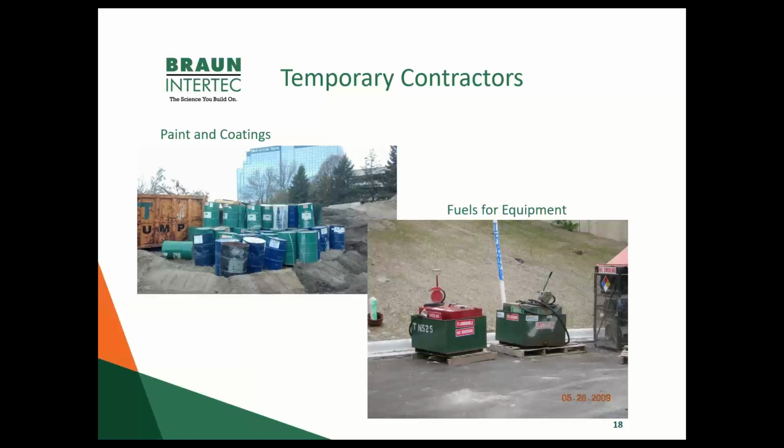Yep, and that goes for temporary contractors as well, because if they bring several barrels of petroleum products on site, one, that's material that has to get managed, but also that could trigger that now the facility overall has a larger aggregate of volume. So you want to make sure that that contractor has their ducks in a row, that they have their spill plan in place, and that they're managing those materials appropriately, and that it is clearly designated that this is the extent of their responsibilities, and that's not on you.